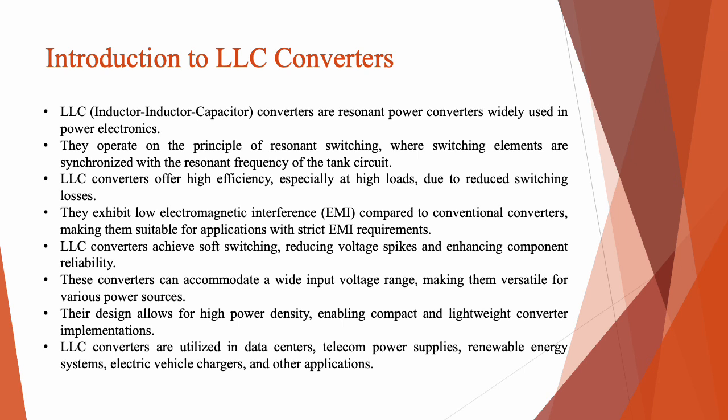For the introduction to LLC converters, they are widely used in power electronics, and LLC stands for inductor, inductor, and capacitor. They operate on the principle of resonant switching, where switching elements are synchronized with the resonant frequency of the tank circuit. Also, they offer high efficiency, especially at high loads due to reduced switching losses.